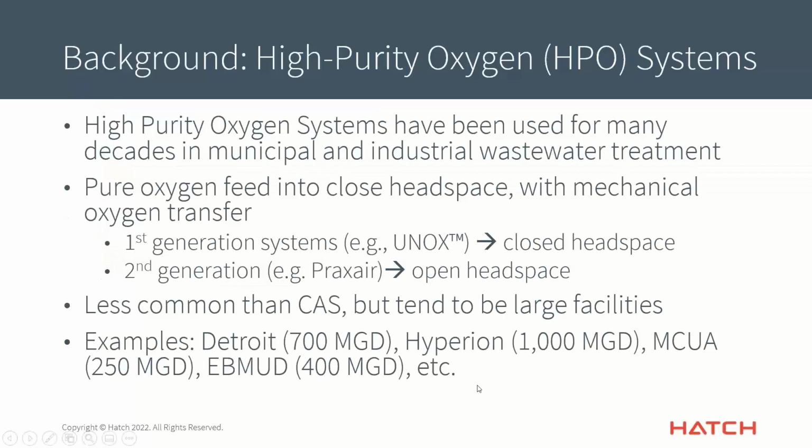All right. So high purity oxygen systems have been around in the activated sludge industry for several decades in both municipal and industrial wastewater treatment. And so the idea behind them, of course, is that instead of air that you blow into the activated sludge, they're using a pure oxygen feed. So I've seen a couple of different kinds of these systems. Sometimes it's 100% oxygen, sometimes it's a mixture of things.